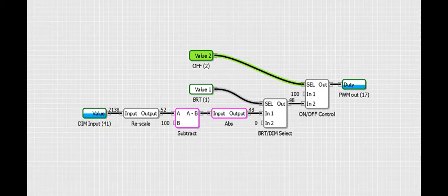All right, this is just a quick video to demonstrate the PoBlocks code that I've written to take an analog input and convert it to a pulse width modulation output to drive the dim function on the UHF panel for the 7-segment displays. So you can see here on the left, dim input coming in on pin 41 is an analog input.